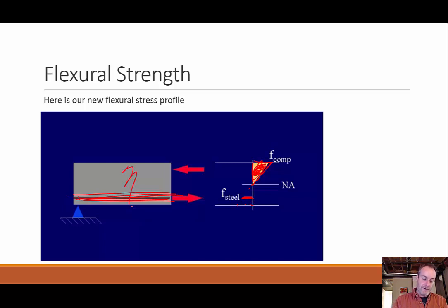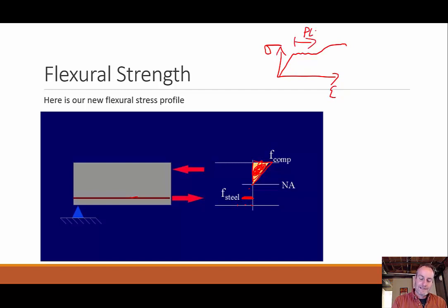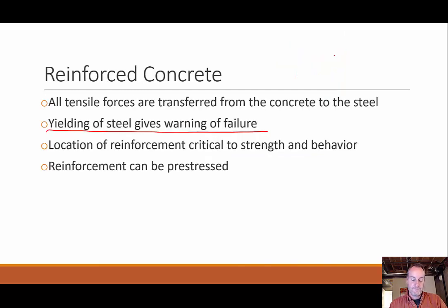You have complete failure. So instead what we want is for the steel, remember our stress strain diagram for steel. It went up and then it had this big elastic part, right? Our plastic part, which means steel can bend and stretch. Well, that would happen if this started to fail. You can imagine the steel is stretching, so the concrete can't stretch, so it starts cracking every which way, but the steel just stretches. Well, it doesn't fail, it just keeps stretching, especially if we still have this strain hardening bit in here, right? So that keeps us from having a total failure.